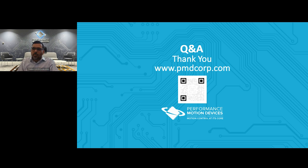So if you look at a mobile robotics application, we have two examples. One is with our drives right at each of the wheels. So they have independent four-wheel motion. And in that particular use case, they don't have a central controller, and they take one of our drives. We can download code to it, and they make it the master, and they daisy chain the other three. So it's a distributed architecture. So the sensor data is coming back, and the first one talks to a Wi-Fi controller